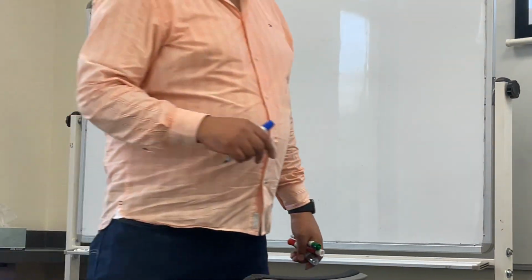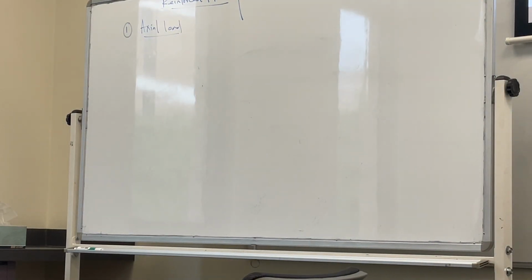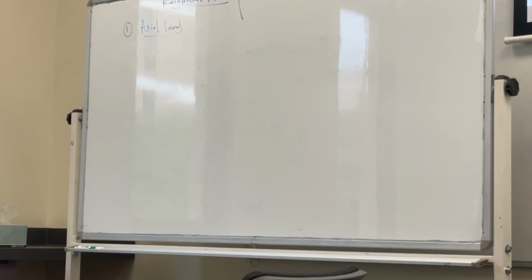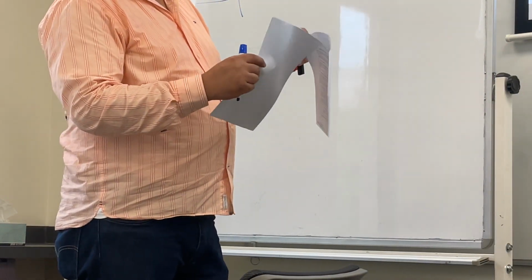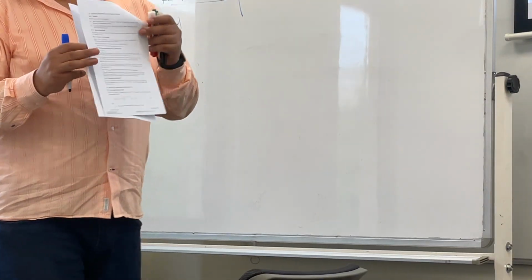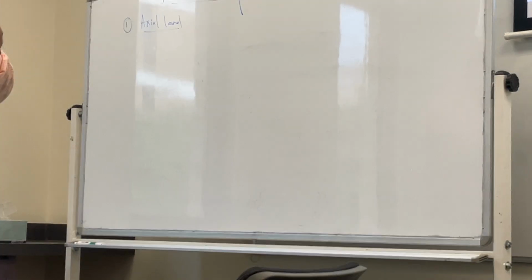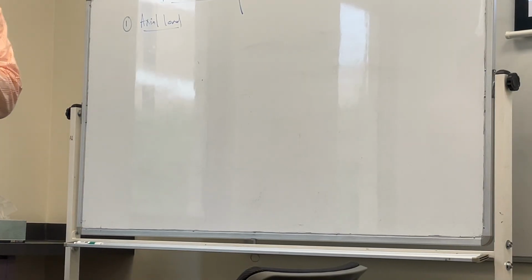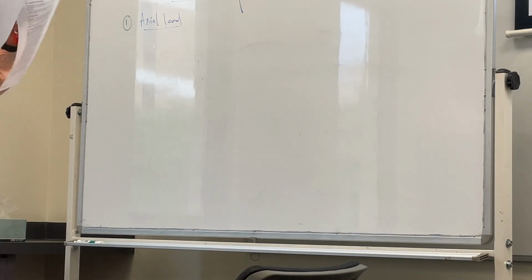What is the maximum axial load? 4.9, 0.5 for the internal. So we have external and internal. The internal is more critical because it carries more load. So what is the formula? It's already factored. Then you have the self weight.